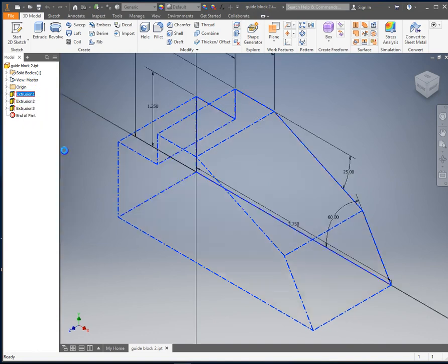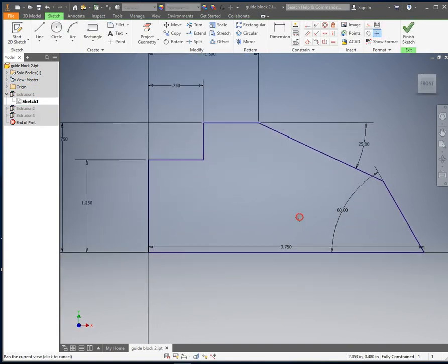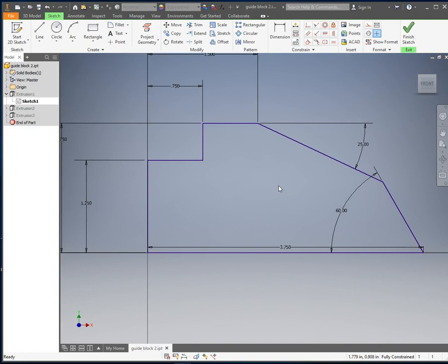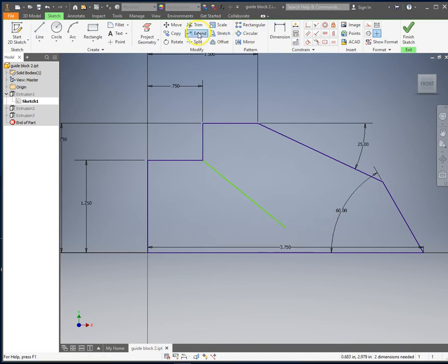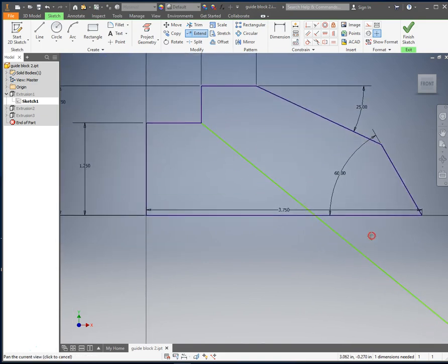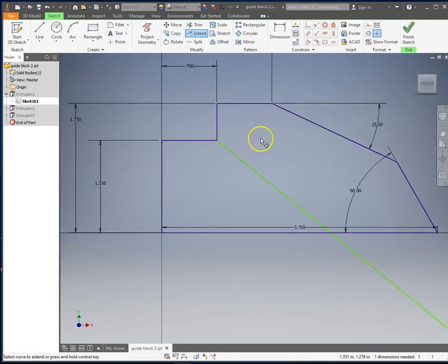Right click, edit sketch. You see this one, we use trim when we're talking about our chamfer, but if I draw a line, let's say from here to here, right click, OK, and I want to extend it, and I use extend, and I just point to the end of that, it will keep extending it, I guess, even without boundaries, because it extended that again.